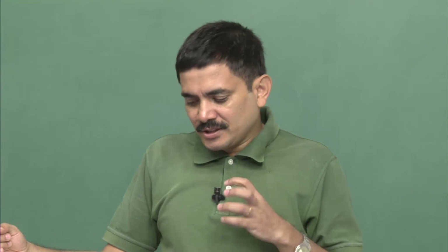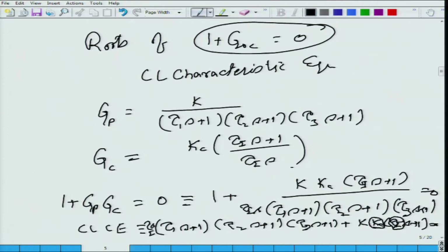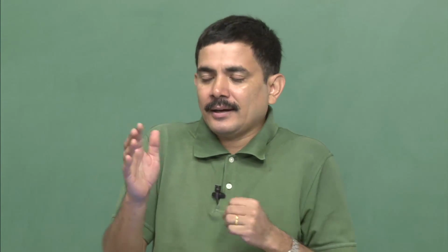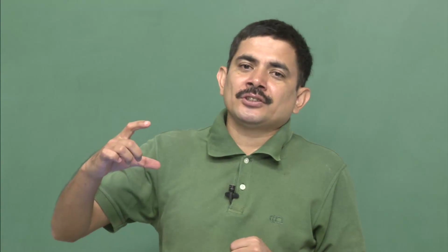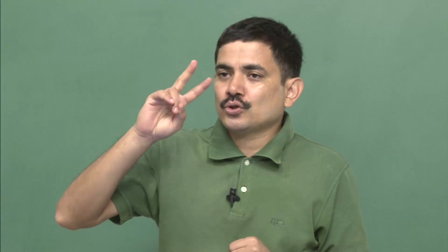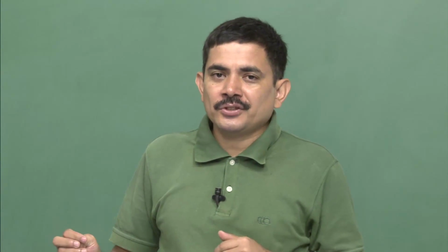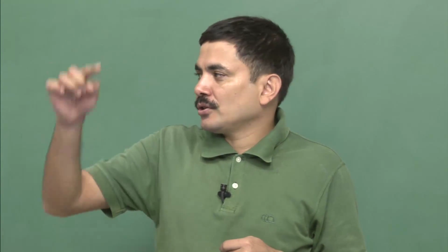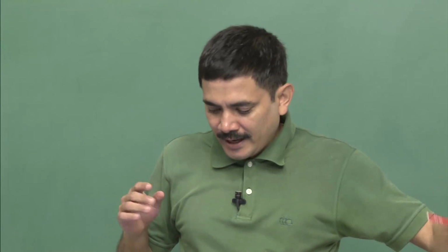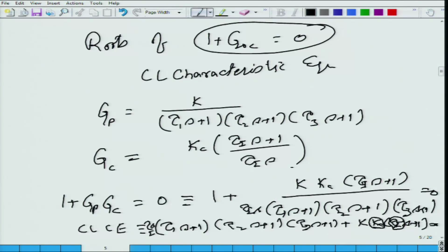And what this is implying is that as you are changing k_c, the closed loop characteristic equation roots are moving from the left half plane towards the right half plane. When you have sustained oscillations, you have at least 2 purely imaginary roots, and when you crank up the gain further, the real part of the root becomes positive, and you start getting oscillations that blow up. Okay.